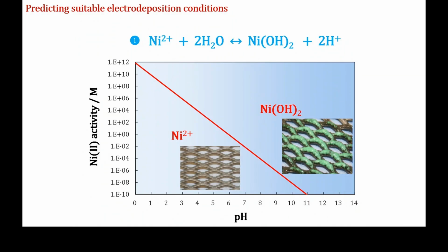We don't want any hydroxides at all when we do plating, because when you deposit from an aqueous species like nickel 2+, or perhaps some sort of aqueous complex, we can get a nice nickel deposit. When we form nickel hydroxide, it does this to the electrode. So it's a highly resistive, non-reactive sludge, right? And this is true for nickel, but also for many other metals. So you don't want iron oxides, you don't want hydroxides of anything, because this is what they look like.